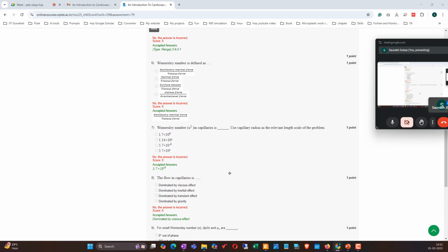Okay, the flow in the capillary is dominated by the viscous effects. Already we have discussed that laminar flow will prevail in the capillaries because of the low dimension. As we know, it is less than 8 microns, sometimes less than 10 microns, the surface effects and the viscous effects dominate, and gradually there will be high viscous dissipation associated.